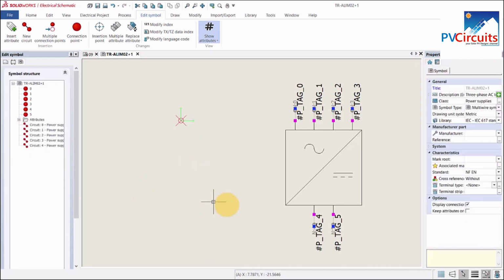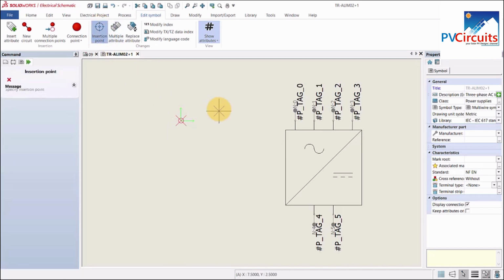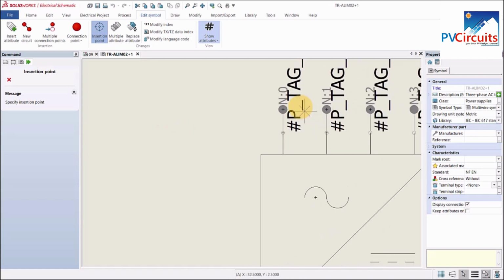Yeah, then when you delete all those, you can see this point, this is the insertion point. It's still far off, so I come here, click on this, then I want it to be inserted at one of these points. But you can see that when I try to go to the center of that dot, it's not picking it, and that is because of this setting here.